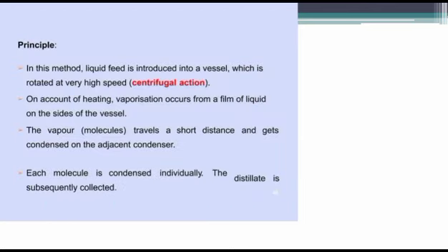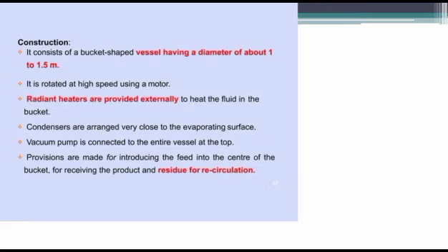Principle: in this method, liquid feed is introduced into a vessel which is rotated at very high speed. On account of heating, vaporization occurs from the film of liquid on the side of the vessel. Each molecule is condensed individually. The distillate is subsequently collected.